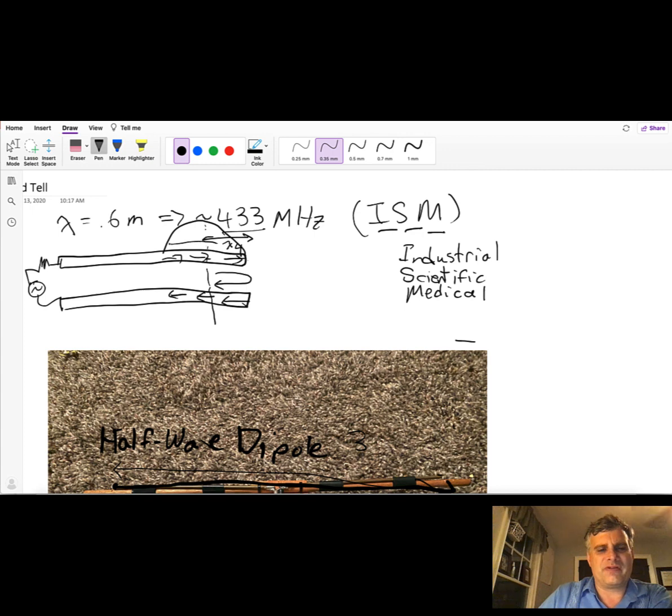And then a quarter of a wavelength later, you get a null. So 1/2 of a wavelength from the end, you get a current null, and the pattern repeats itself for as long as the transmission line is. This is something basic you learned in 3025.